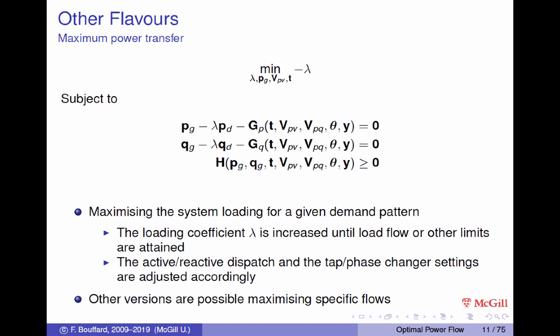So they are trying to find how much transmission they can allocate to carry out transactions across different power system areas based on stability limits, thermal limits, etc. So you would solve a problem like this to determine how much capacity you can actually allocate for these transactions over these interfaces.